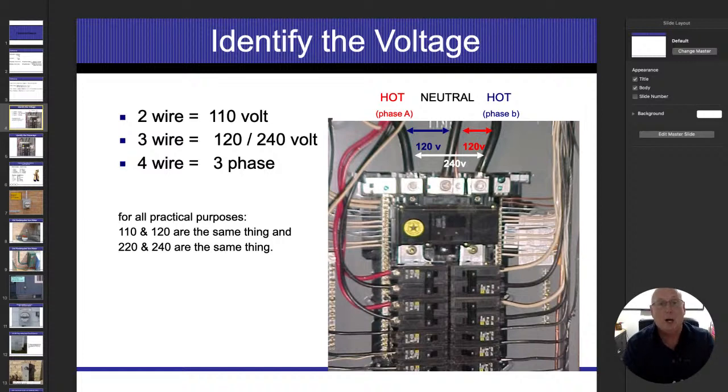So if I had 100 amps flowing on the right side energized conductor, and I had 0 amps flowing on the left side conductor, I will have 100 amps flowing on my neutral conductor. Since all 3 of these wires are designed to carry 100 amps, not a problem. So let's take another scenario. 100 amps flowing on the right side conductor and 100 amps flowing on the left side conductor. Since one is positive and the other one's negative, positive 100 plus a negative 100 actually equals 0. So if they're both the same, I will not have any electricity flowing on the neutral.